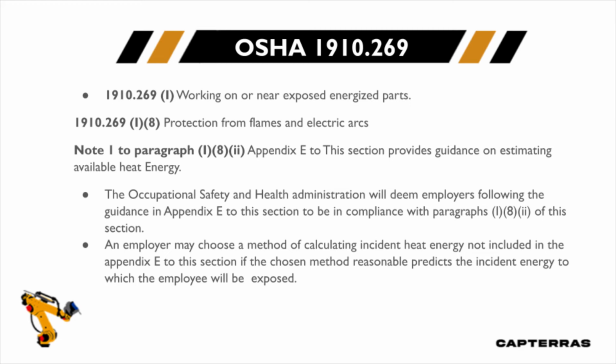Now again, we can always go beyond this. In some cases, this is less stringent than what would be called for in NFPA 70E. In some cases, there are additional requirements that go beyond NFPA 70E in protecting against flames and so forth. So it's important. Also, as I mentioned earlier, if you use live line tools or anything like that, please become familiar with this standard, because the requirements for grounding, live line tools, and control of hazardous energy can all be different when you get into substations, underground, or overhead medium voltage distribution, and cogen, etc. By the way, some sites are actually indicating that if you have on-site solar, they're treating it as continuous power generation.